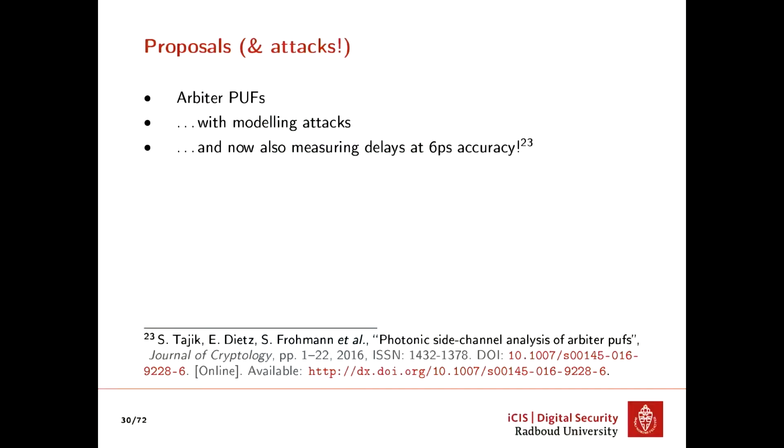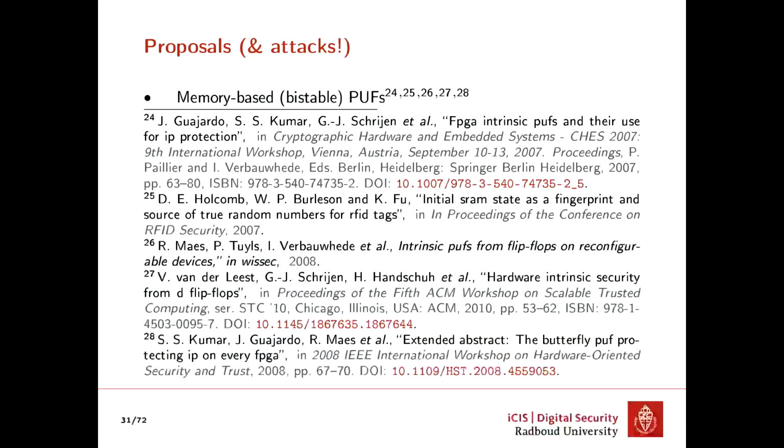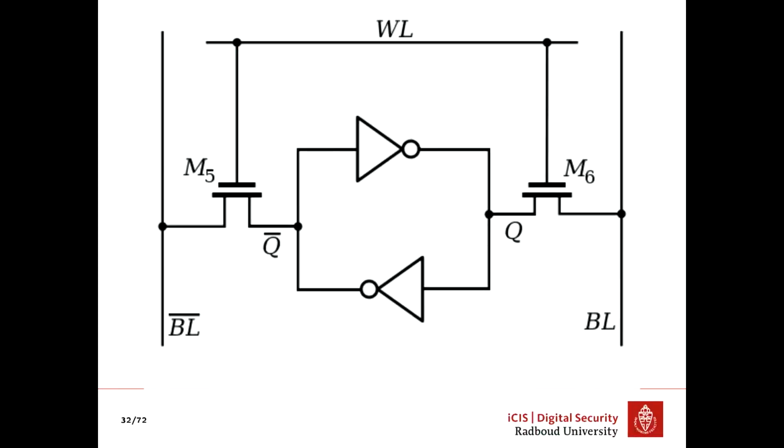And you can also use optical measuring of signals through devices at 6 picosecond accuracy. So these things might not be around for much longer. Then there are memory-based PUFs. They are based on bistable memory, which basically looks like this.